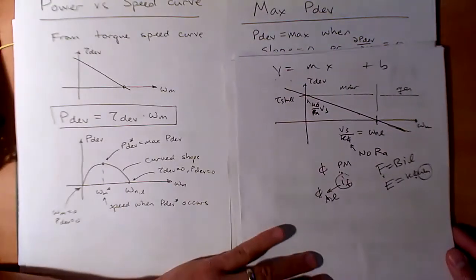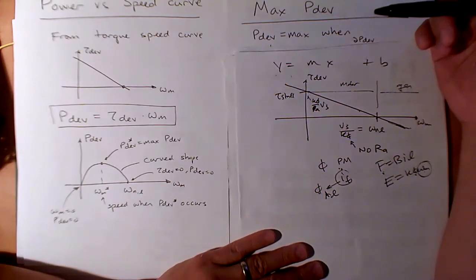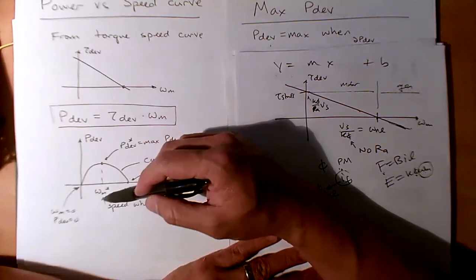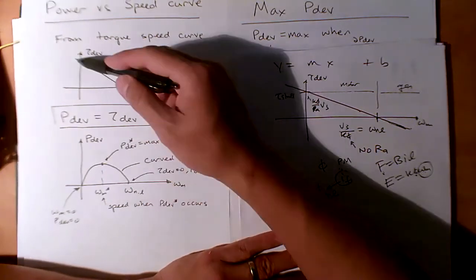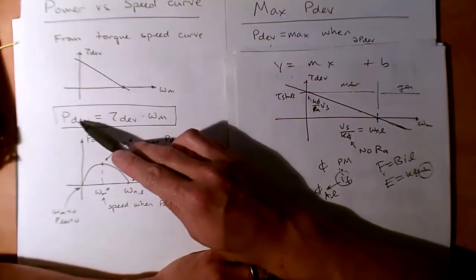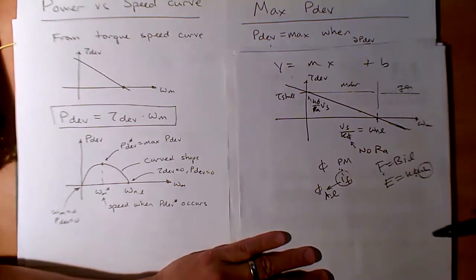So this is just to remind us of the calculus that goes in there. What I want to see is, what is the equation that dictates finding this? Now I'm already telling you that it's about half. Half of the stall torque is the optimal torque, half the no load speed is here. And the other question is, what is the power developed? How would this power developed depend on RA, phi and VS?